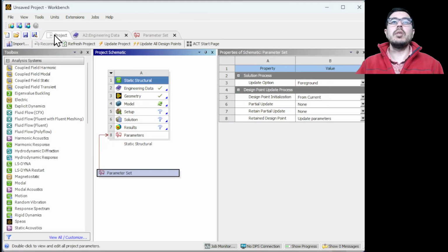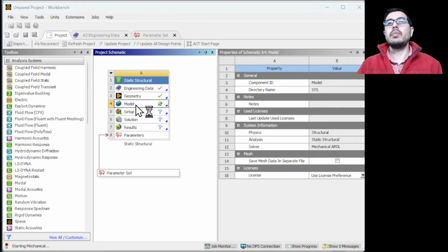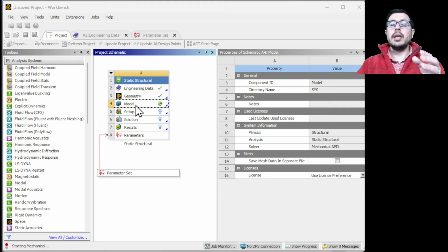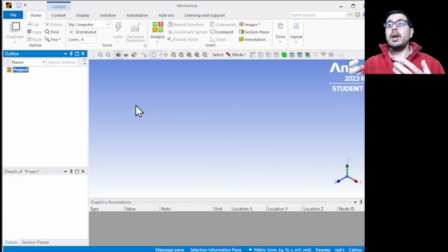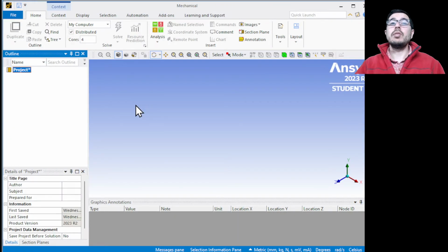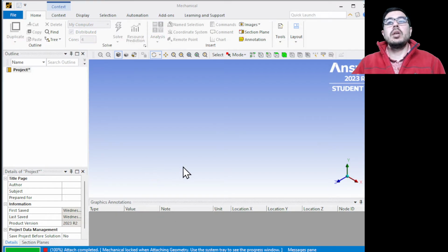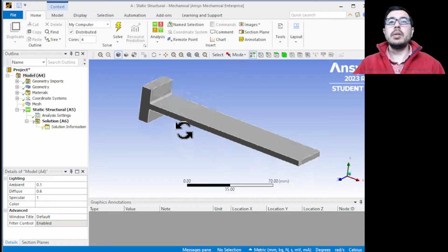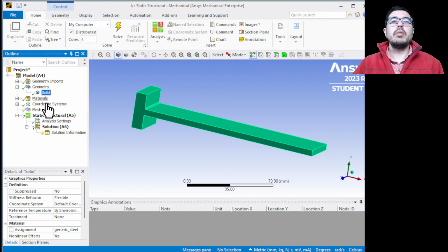So now let's go into the model. And for this, what we're going to do is apply that transverse load, that cantilevered load of 300 newtons on the end. And what we expect is that we'll get a value that is at least 360 megapascals. And that's because we have the stress concentrator in the corner. So the geometry comes up, good, or it's almost up, okay. We want to make sure that we have the use of our generic steel, so that's good.